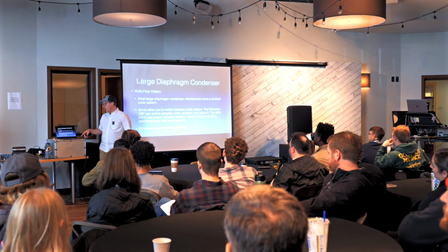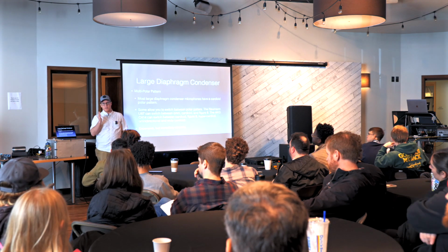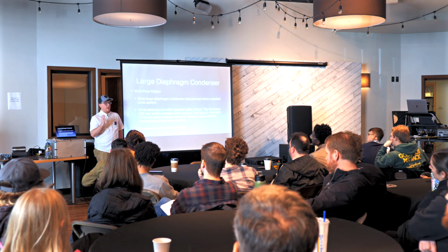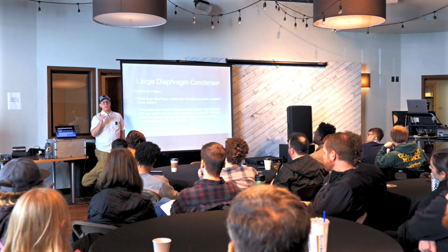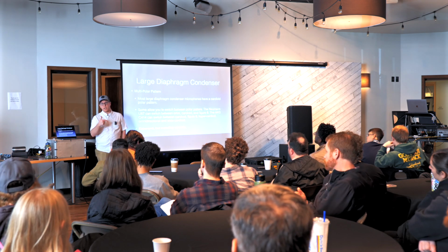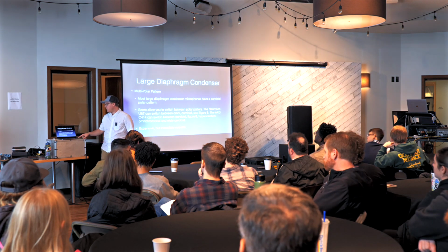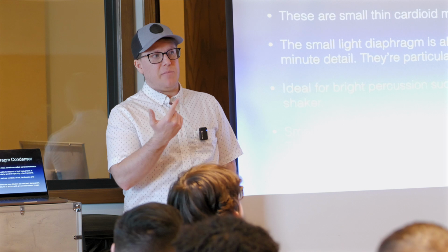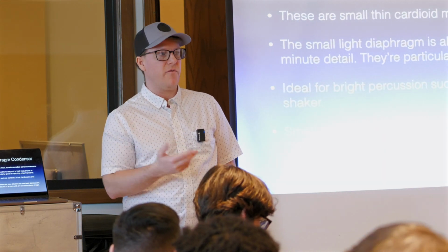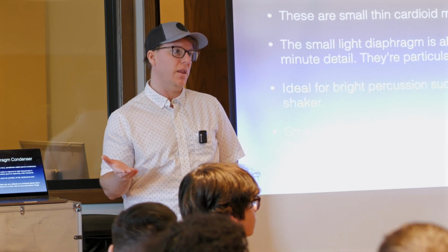Those microphones specifically also have a high pass filter that you can change from, I believe, 40, 60, 80, and then also a decibel decrease. So if the sound source is really loud and you want a 20 dB decrease, you can just push a button and it does that automatically. Great microphones. AKG makes a similar version called the C214, which is a more affordable version. You just don't get the multiple polar pattern switch on that microphone.